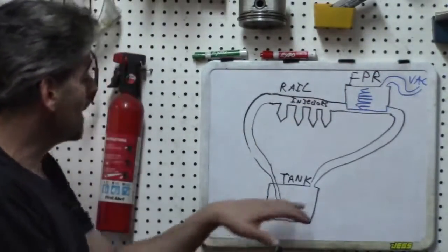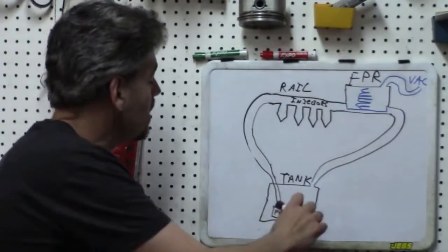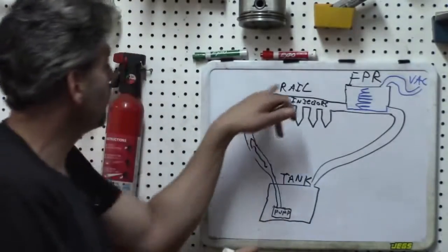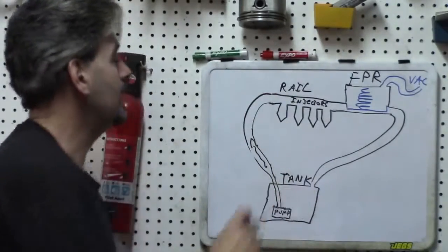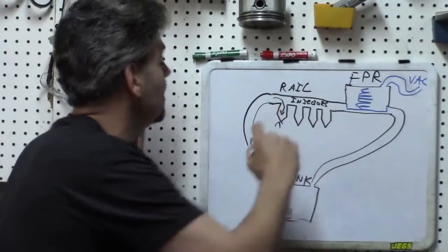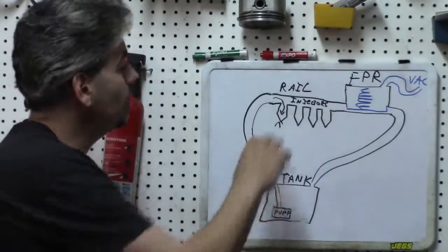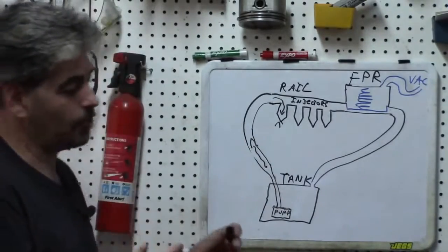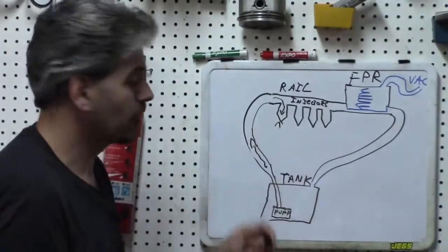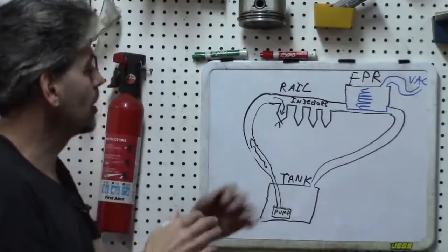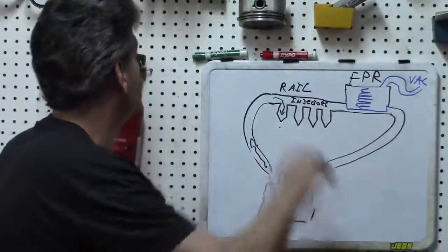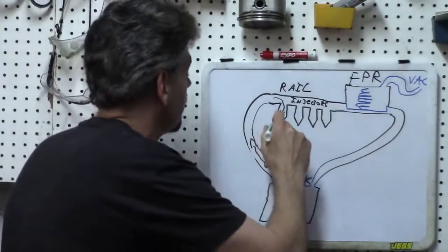But basically, here's your fuel tank. You have your fuel pump, which of course drives up fuel to the fuel rail. You will have your injectors here, and of course the fuel goes through the injectors. The injectors deliver fuel into the intake manifold, and to be specific, there are newer designs called direct injection, where the injectors deliver directly to the cylinder. We're not really going to cover that, but basically, let's actually put fuel in green here so it stands out a little bit.